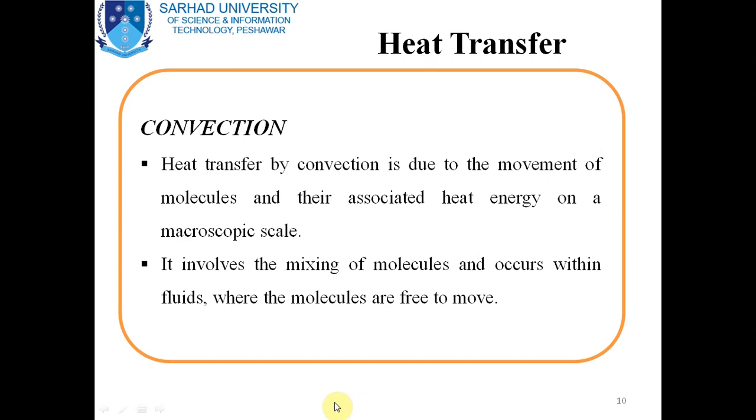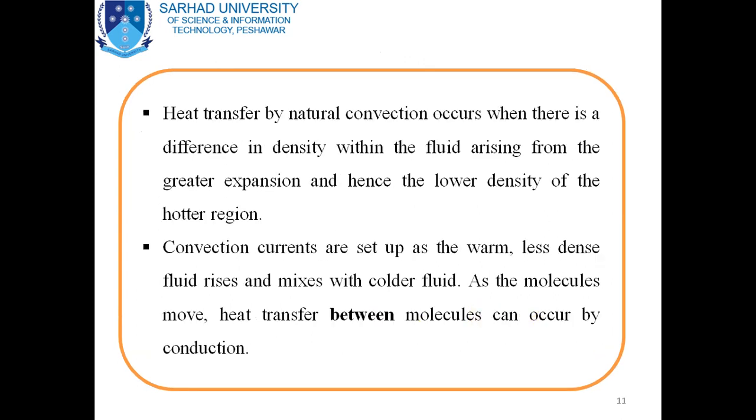It involves the mixing of molecules and occurs within a fluid where the molecules are free to move. Heat transfer by natural convection occurs when there is a difference in density within the fluid arising from the greater expansion, and hence the lower density, of the hotter region.